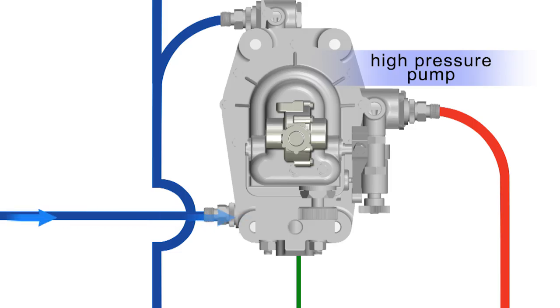Also remember, when working on any component from the high pressure pump onwards, you may be exposed to fuel under high pressure. Always wear your safety glasses and gloves.